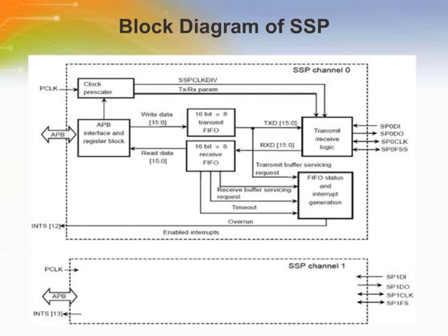The USB device controller consists of the core part called the UDC2 and the bus bridge part called the UDC2AB, which enables connection with the AHB bus. It has the below features: conforming to Universal Serial Bus Specification Rev 2.0, supports both high speed and full speed, supports chirp,